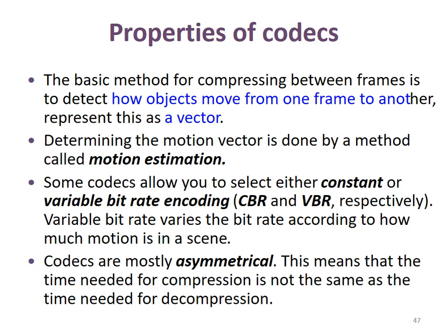Once we can estimate the motion vectors, then you can see the basic compression concept is to replace the rectangle with the rectangle in the second frame directly. Because we know this person is moving from the previous frame, and we know its previous positions. So this achieves the goal of compression. Once we can, for example, paste the rectangle directly here, then we don't have to record anything of this region.